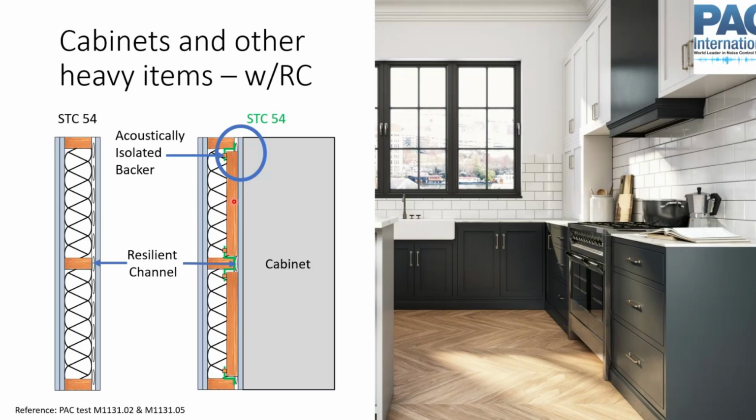You also need to make sure that whatever that thing is, it's obviously strong enough to hold the cabinet, and a cabinet not just empty, but full of dishes and all of these kinds of things. But when you do that, if you break that transmission path, you can bring the wall back to roughly its original level of performance, close enough, right? In this case, you get the same STC rating.